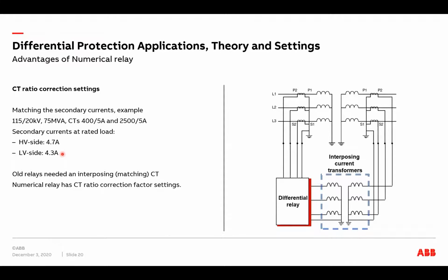But in modern relays, we don't need an interposing CT because this is done with a setting, compensating for the current differences between the primary and secondary side.